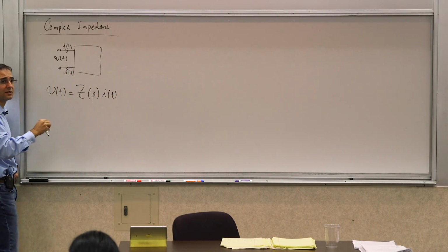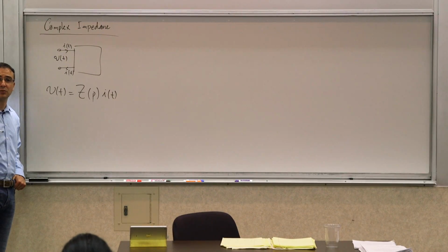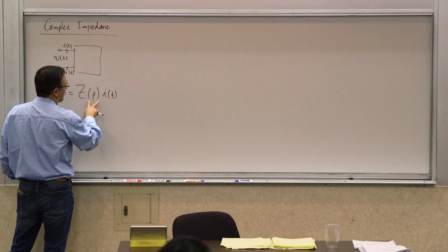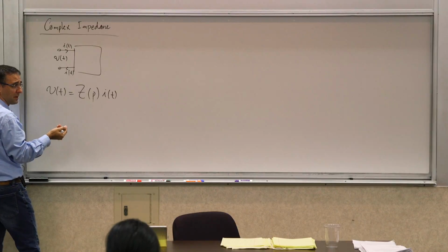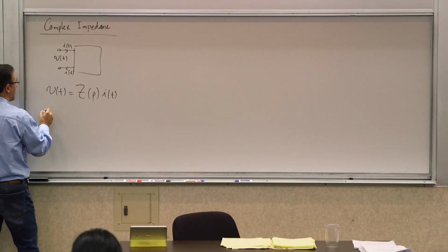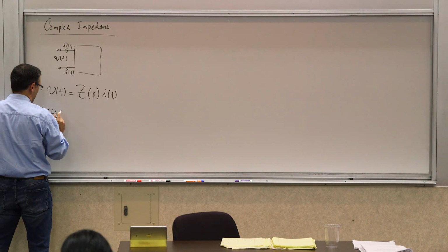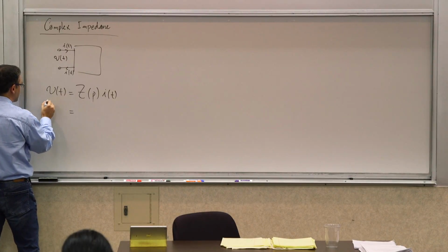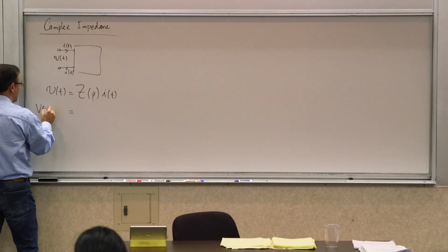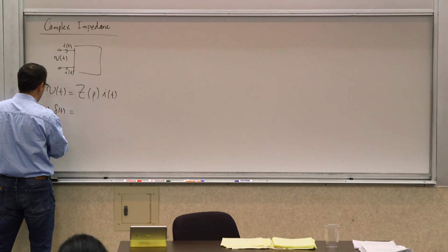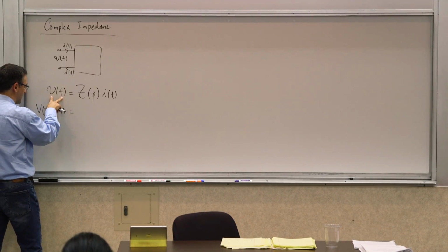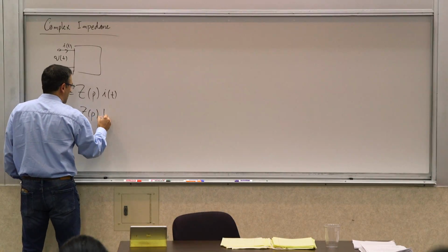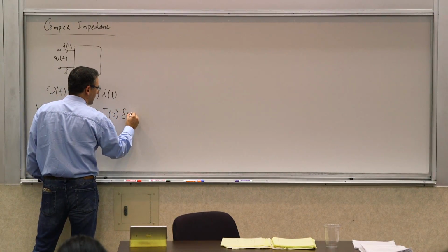So we had this operator in terms of p, and if it were a lumped network, then you would get basically a rational function. And what happens is that it operated on this. There was another way to think about this, which is basically the Laplace transform, saying that since we know that V of t is a convolution of the system transfer function with the I of t, or in other words, you can write this in the operator form. You can write it as V of p operating on delta of t. You remember these were the operators that generated this voltage off of a delta. It would be z of p times I of p operating on delta of t.